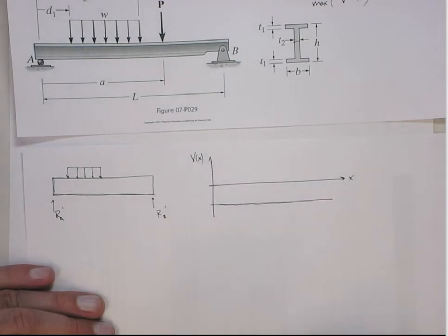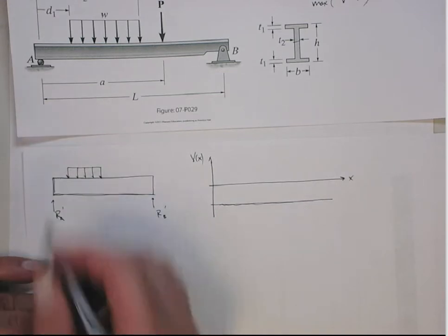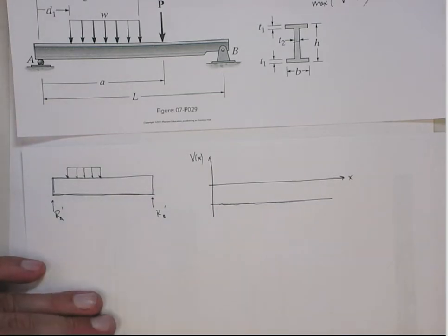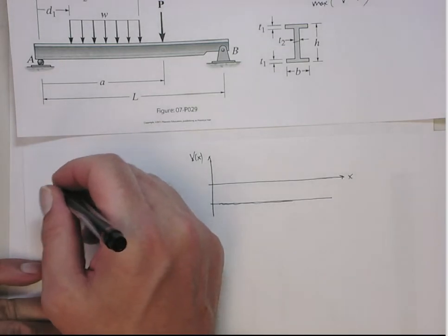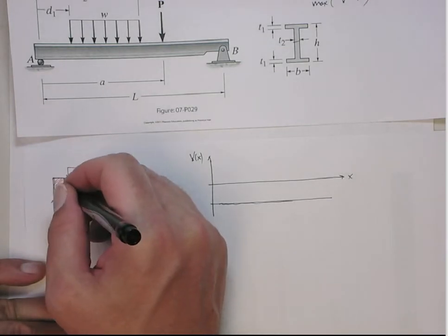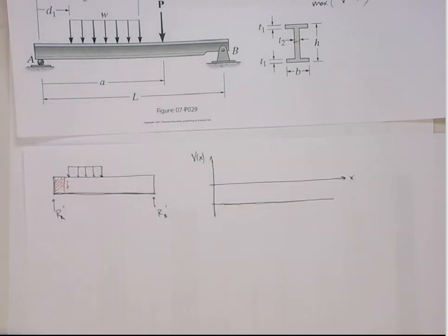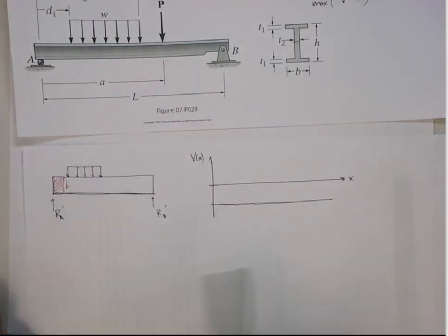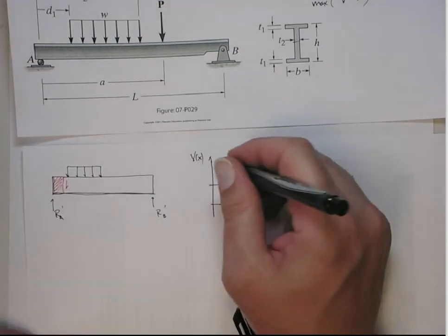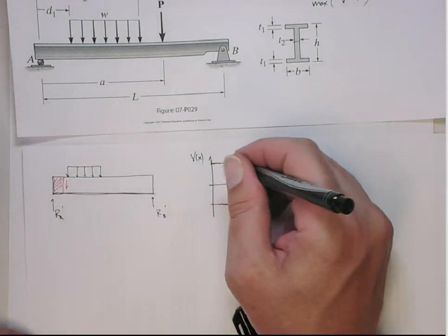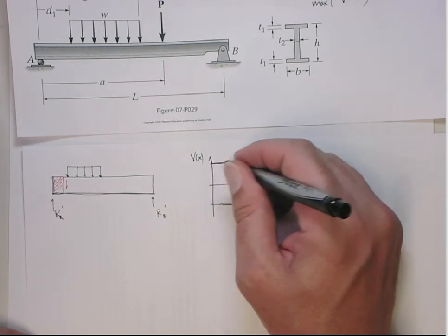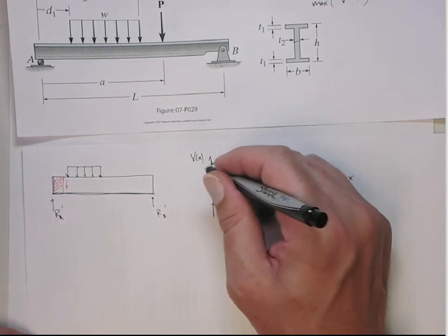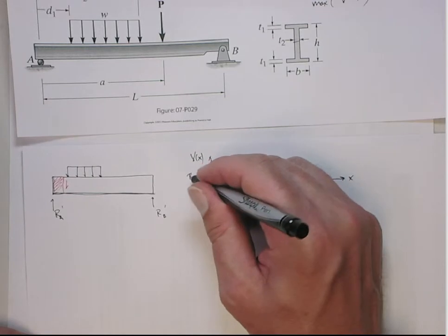All right. So we all should be experts at shear bending moment diagrams. So if you look at just this section when you start to go from A, just prior to where the point force is, right? That's the shear force acting downwards. So the shear force is going to be constant on that, and it's going to be equal to Ra prime. Okay? So now this value is going to be Ra prime.